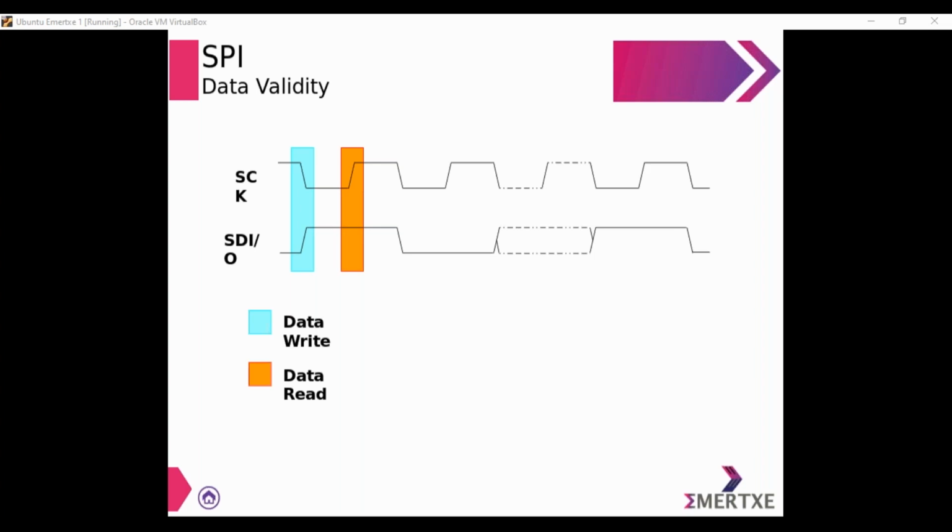So data transmission and reception happens with respect to the clock pulse, either with edge triggering or with level triggering. Now the question is, when does edge triggering happen and when does level triggering happen? That completely depends on the SPI manufacturer. It depends on how the chip is working and which functionality has been incorporated.